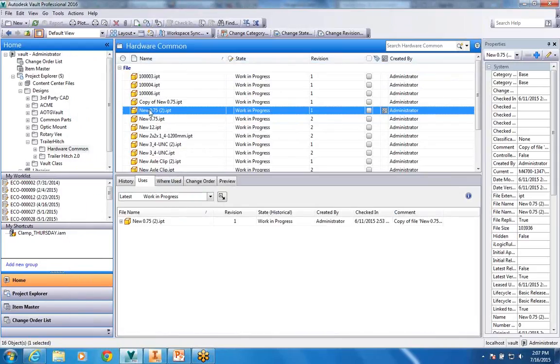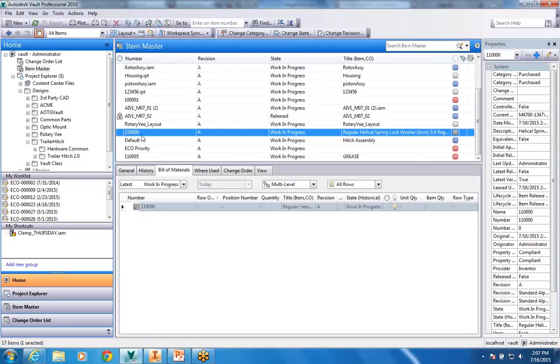So I apologize for that. But when you create an item for a particular part, notice over on the right, it shows if there's a link to the item, and we can just hold Control and click on that, and now it brings you right to the item in the item master. So it's a nice way, if you're working with files, to get right back into the item master to the right spot. Obviously, sometimes on the file side you might just have it called bracket or a more generic name, but once it's in your bill of materials, we want the part number. I usually encourage putting the part numbers in on the file side as well, so you have them available, and then just copy over the same number into the actual item master.